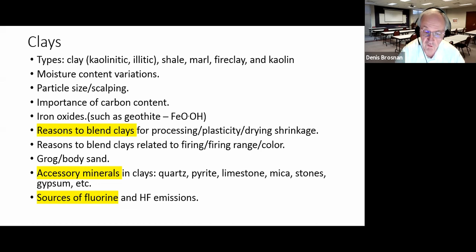Clays can contain sand, of course, because they're mined from the surface of the earth. The amount of sand is important in the quality of the product. In molded brick products, sand is added. There are two ways to make bricks: by extrusion, that's lower moisture content, and by molding, either by hand or machine, usually by machine. And molding is a process of higher moisture content. So sand is added to reduce the drying shrinkage.